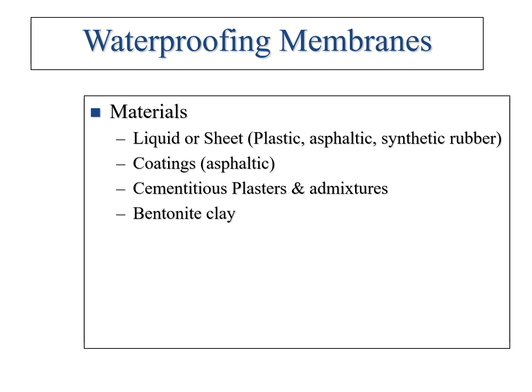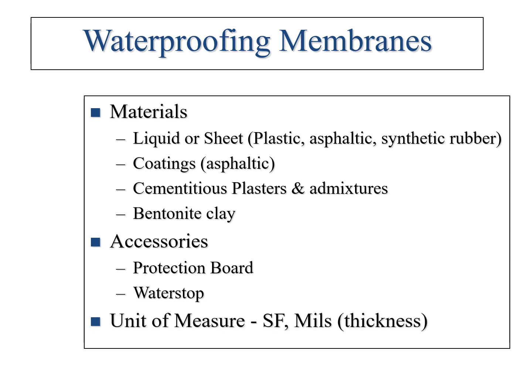And there's even this item of bentonite clay. Clay being one of the oldest methods, really the oldest method being used, is pretty much impervious to water movement, so you can actually coat the foundation with this clay mixture. Then there's a few other ideas that you might have, which is called a protection board or a water stop. And just to say, the way these are measured, of course, is by square foot, because the foundation wall is figured almost like painting on a wall.